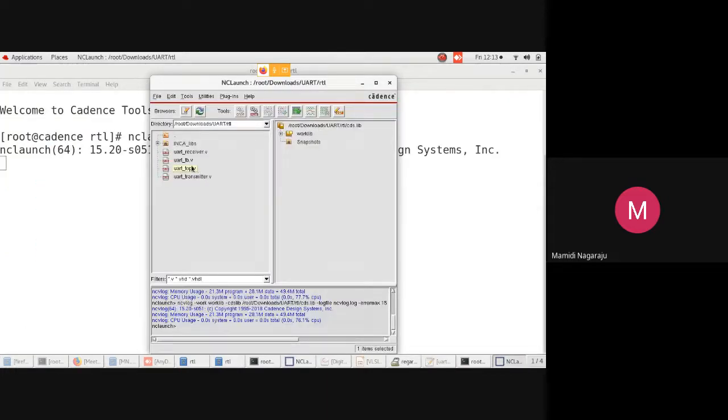So when I'm doing the test bench compilation here, now you can see the tool is showing that it is expecting a semicolon at the test bench, line number 10. So the tool is very interactive. It will show whether you have any errors or not.